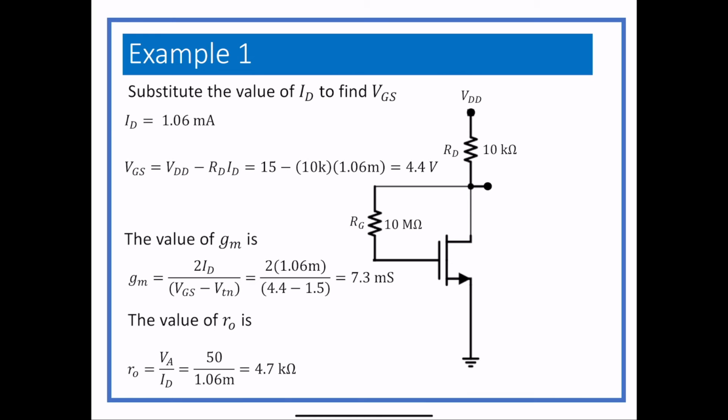So now that we've done all that, that's all we need from the DC circuit. That's it. We need GM and we need R out. If there is no R out or VA or lambda given, then we don't worry about R out. But we do need to find GM. Once we have found that value, now we go and use the model to actually add values in.